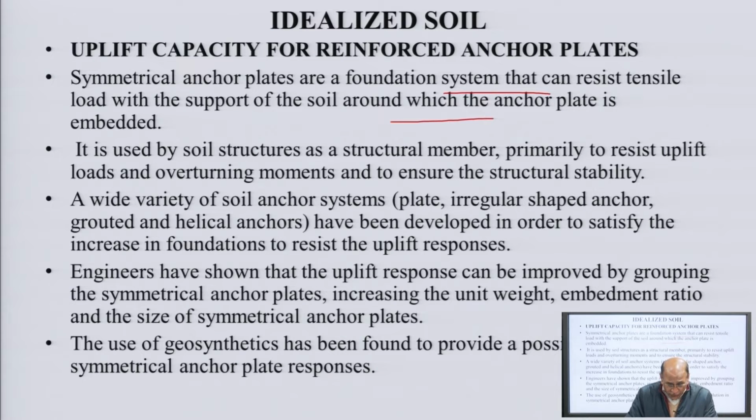Engineers have shown that the uplift response can be improved by grouping the symmetric anchor plates, increasing the unit weight, the embedment ratio and the size of the symmetric anchor plate. The use of geosynthetics has been found to provide a possible solution in improving symmetric anchor plate responses.